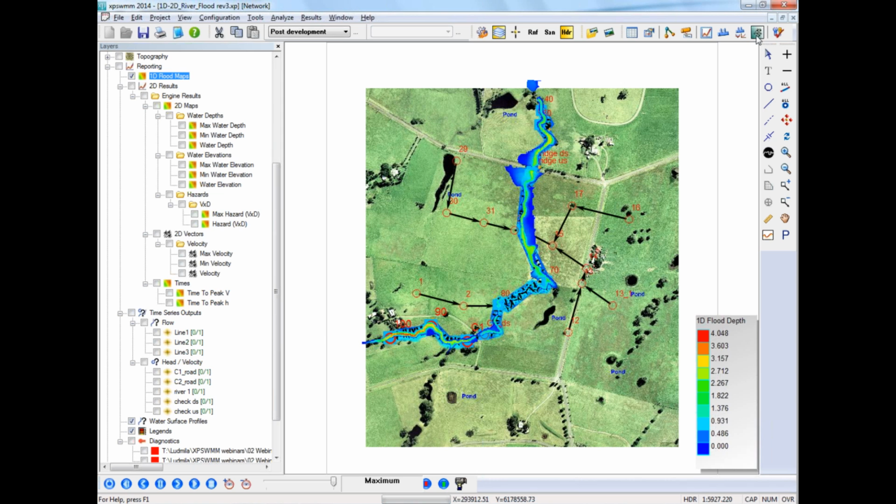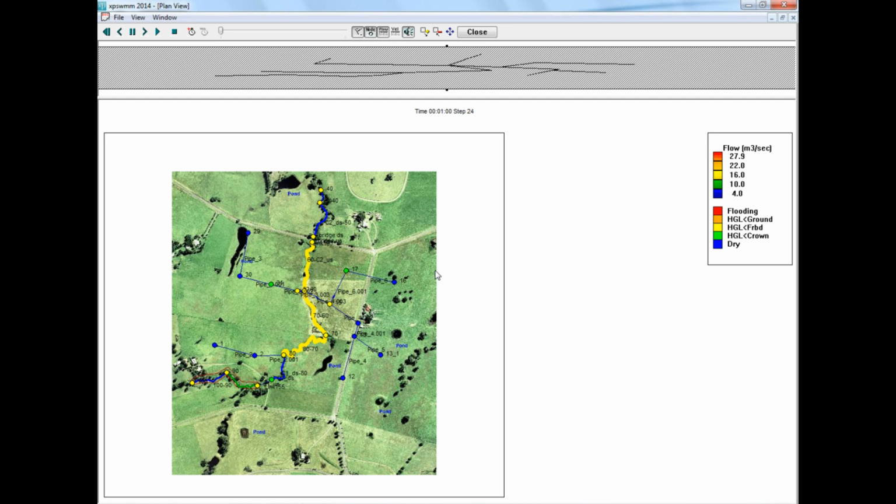There is a dynamic plan view. And this is now the plan of the section, and looking at the top of the screen, I could either show the flow or the velocity. So I can look at both, and I can run the analysis of this in kind of real time, and you'll now see flows in the links and flows through the nodes, and these are shown in the legend on the right-hand side. So if we had red flow in the links, this is telling me that we would be up at something like 28 cubic meters per second.